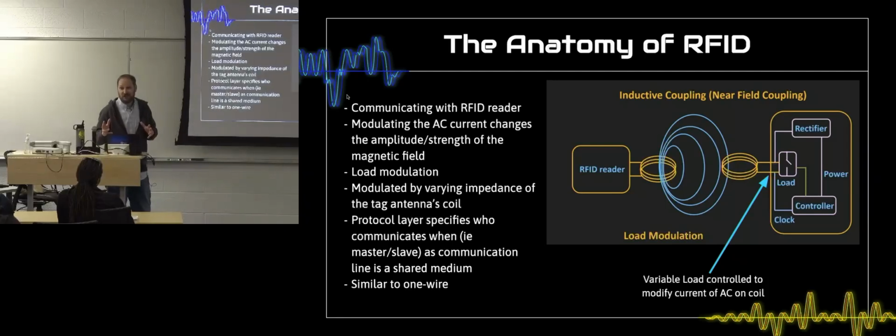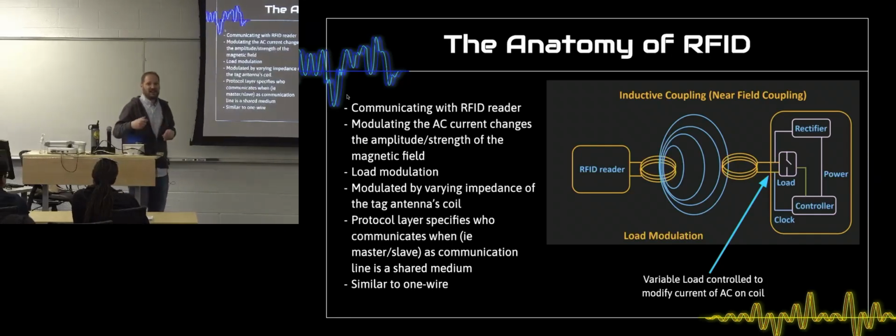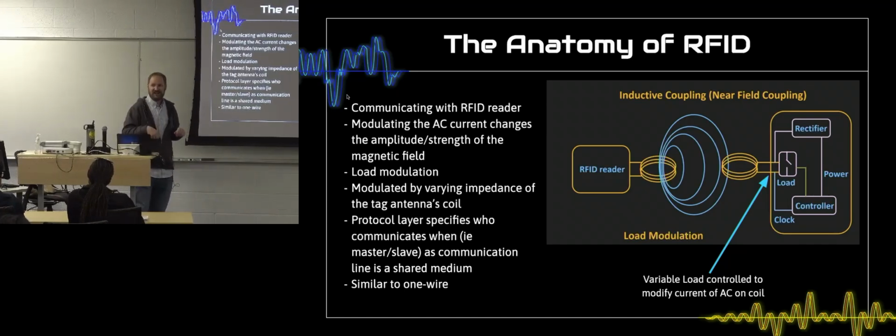The analogy for far field stuff, this is the one where we have propagating electromagnetic waves, is that I am an RFID reader and you are RFID tags, but you don't have any power source, so you can't shine any light back at me. I take out a flashlight, I can send AM modulated light to you, but you can't send it back. So what you do is you take a signal mirror out, just a mirror, and you hold it up and I shine my light continuously and you bounce that light back to me and you modulate it by turning the mirror up and down.